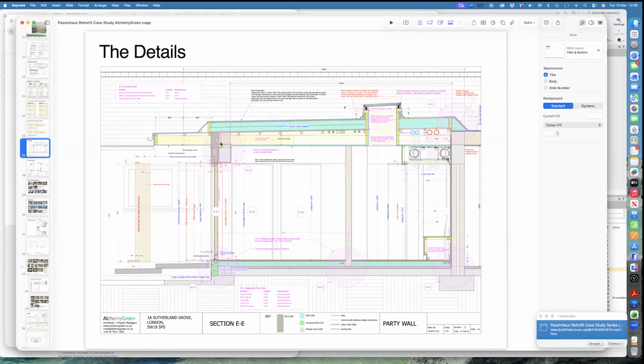It's one of the attractions of it, actually. We did what we could to avoid it, to close out as many thermal bridges as possible. For example, over the front door, that concrete beam is well wrapped, but in other places, like at the party wall, the party wall is vulnerable.